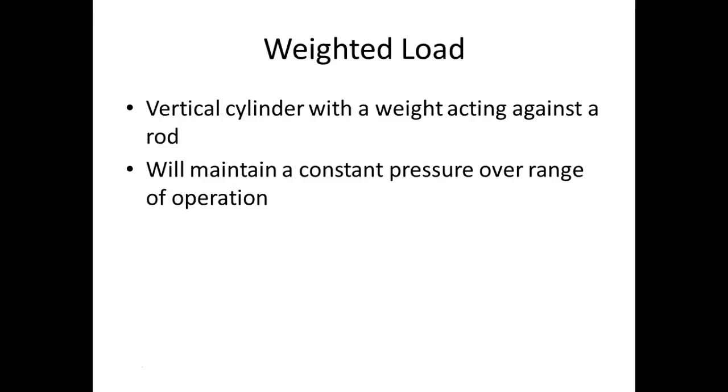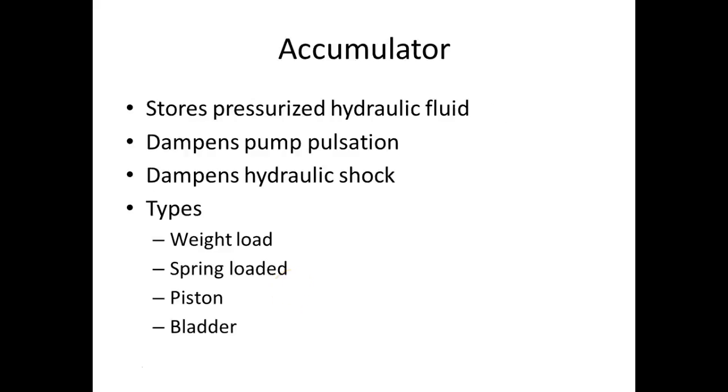An accumulator is nothing but a device that maintains hydraulic pressure even though your pump's off. So a lot of your big industrial complexes will have them, because most of these guys cannot afford an unorderly shutdown. Now, of course, if you do use electric power, it gives them the ability to orderly shut down, right? To set something down that's being picked up, to move things out of the way. But they've got to have time.